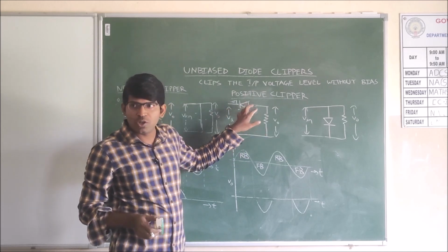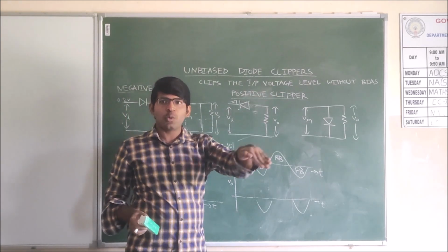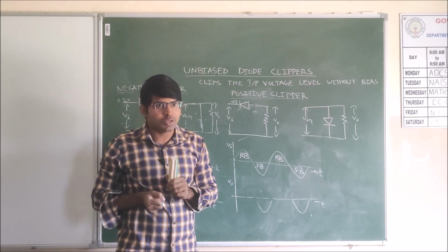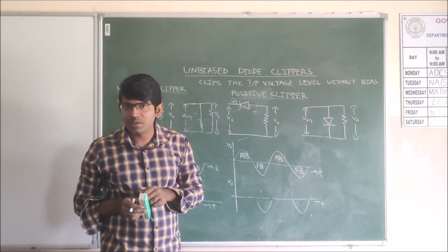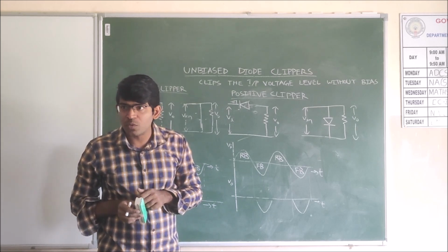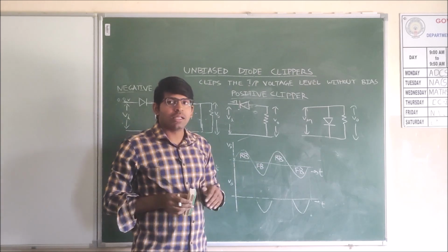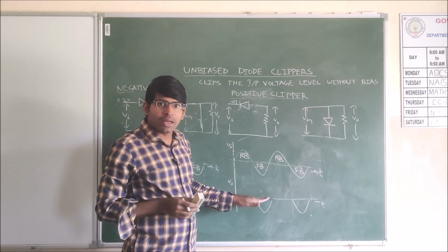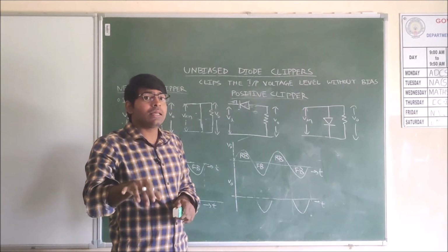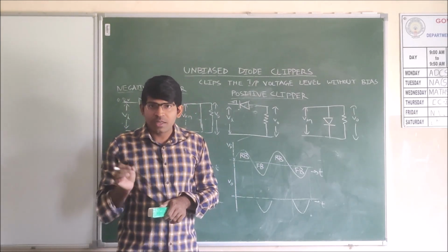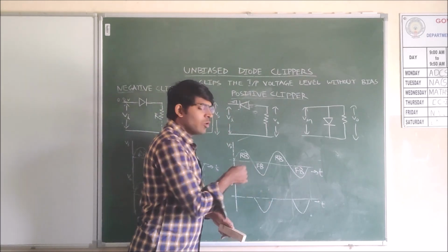If we supply minus 0.6, the diode will take that voltage but will not give any voltage to the resistor. The 0.7 voltage drop in the practical scenario makes the entire negative waveform not appear across the load.